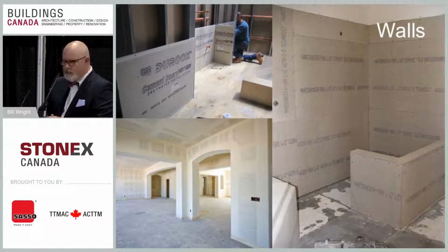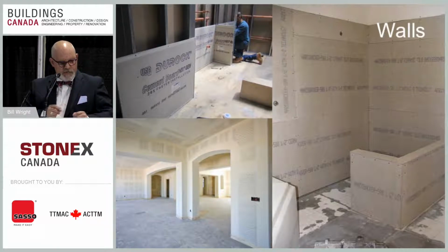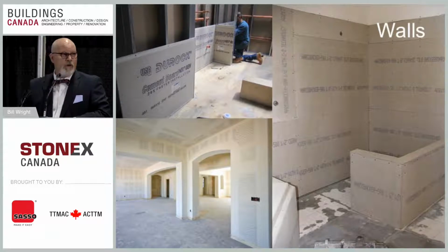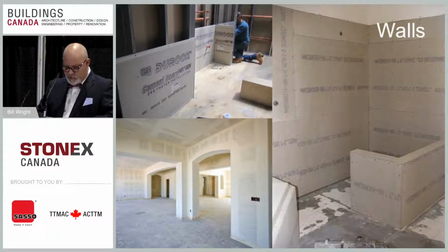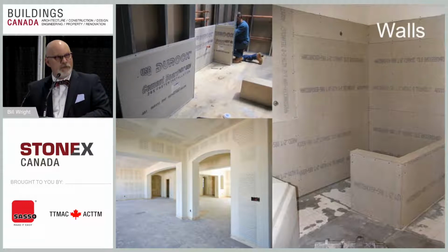And the general contractor was quite adamant that that hadn't been the case. And I walked in, and the first thing I saw was they were installing the same mosaic over the same mosaic in a shower stall. So they had this white 1x1 in the shower, and they're putting another layer of it over top of it. And I thought, well, that was kind of strange. And then I go on to the site meeting, and sure enough, we see this leopard spot wall, and the general contractor was adamant that they hadn't spot bonded it, and I asked the contractor, did you spread the mortar on the wall? Yeah. And I said, and then you went back into your bucket because the wall was a little uneven and you threw 6 blobs on the back of the stone. And he says, yeah. And I looked at the general contractor and I said, I told you.